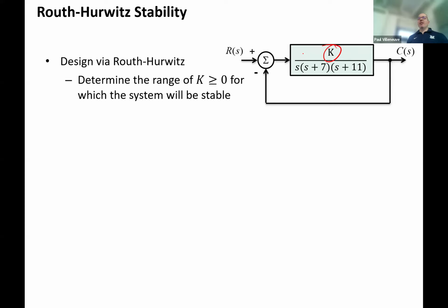Why use 4 to 20 milliamps? Because between 0 and 4 it can fluctuate, but it will be 0. So even when you press a button, the thing about pressing a button is these are all run through controllers. You'll actually have a controller sitting here, and then that's outputting the 4 to 20 milliamps.